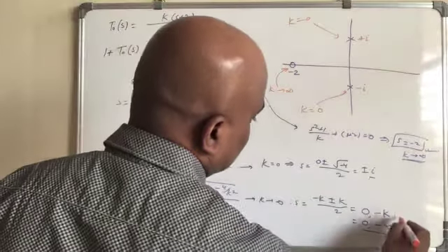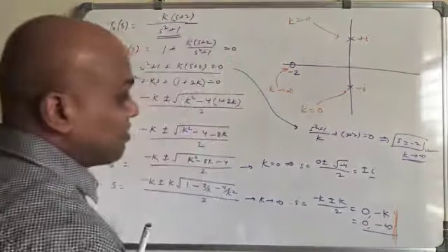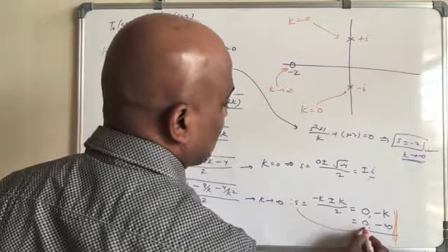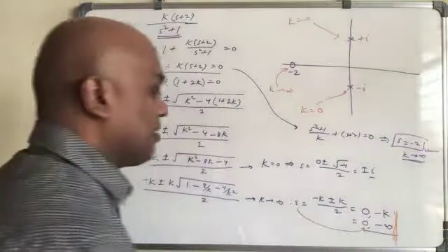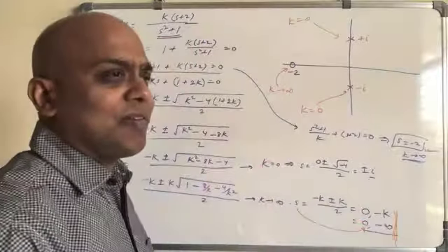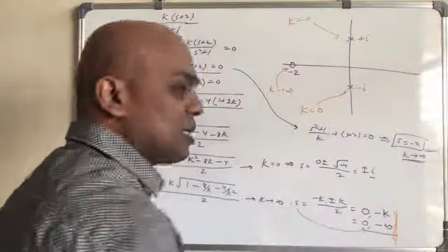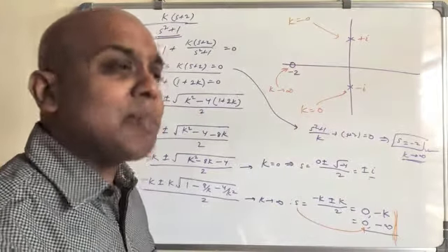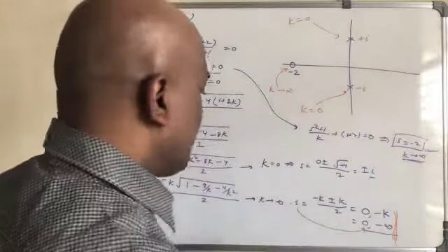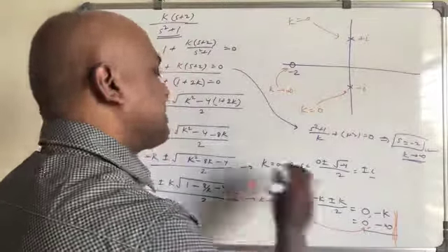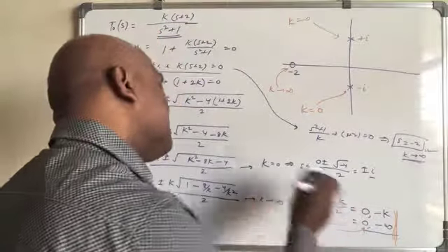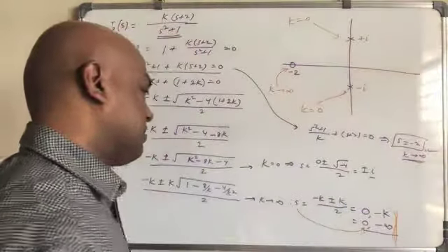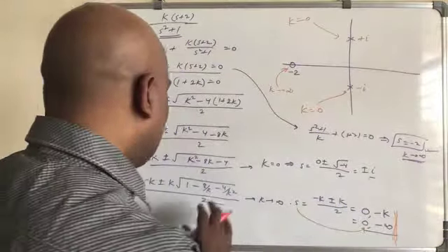Other this one, we have to find out whether really s value can be 0. Let us say we need to test whether s equal to 0 is on the root locus or not. If we did something like this one, we may be making a mistake, so how do we test whether we are making a mistake here?